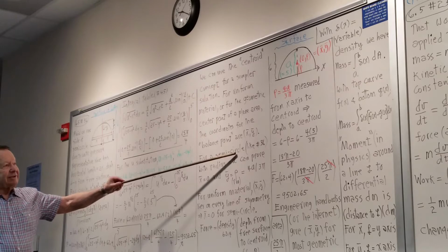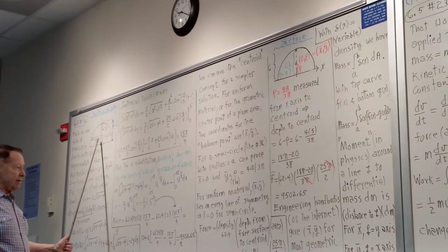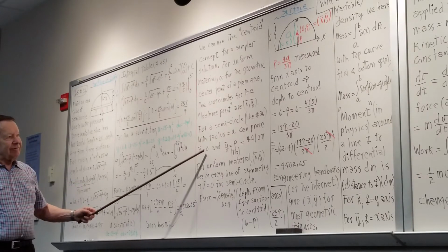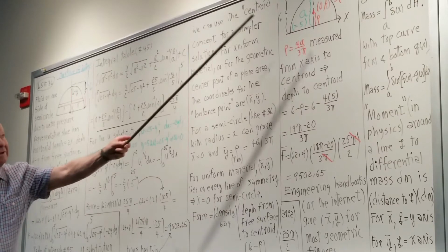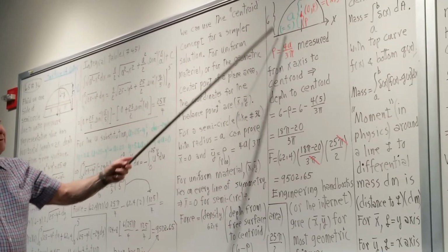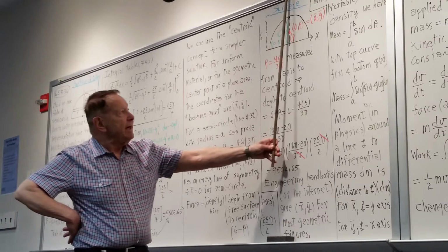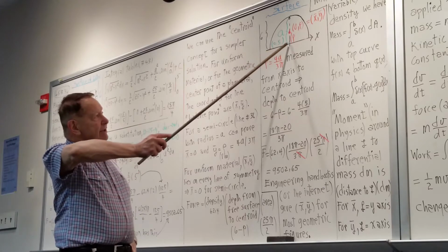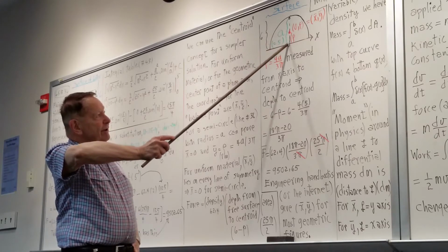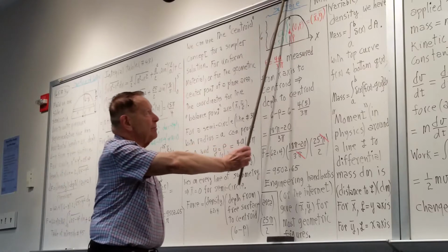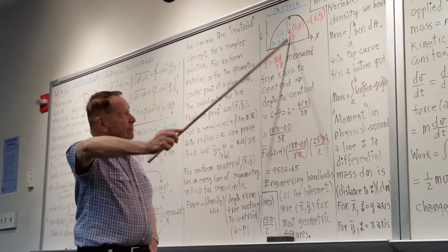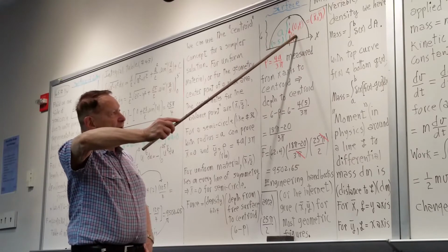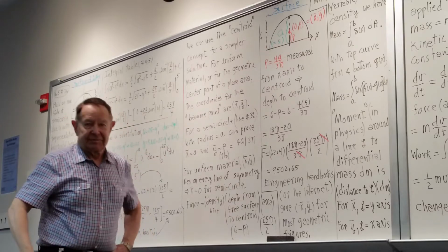If you have a semicircle like this problem, and the radius is A, you can prove then that you have a symmetric figure on either side of the vertical axis. And I was just saying that your centroid will be on every line of symmetry. So it would be on this axis at some point up in here, a distance rho, this is the Greek letter rho again, from the x-axis.